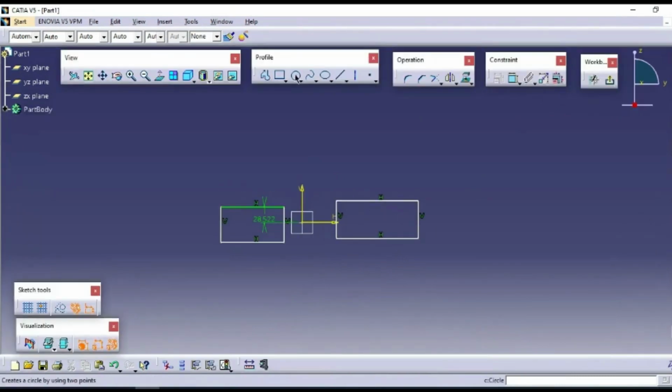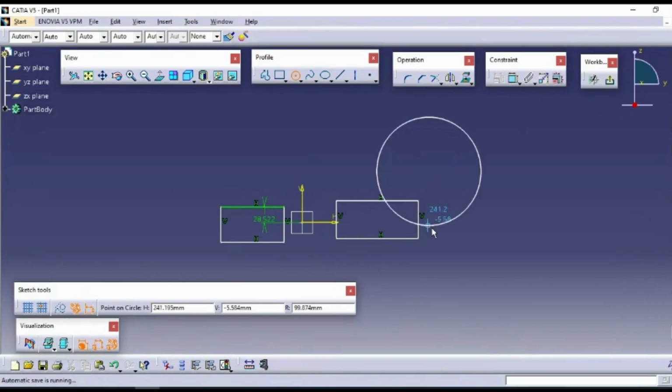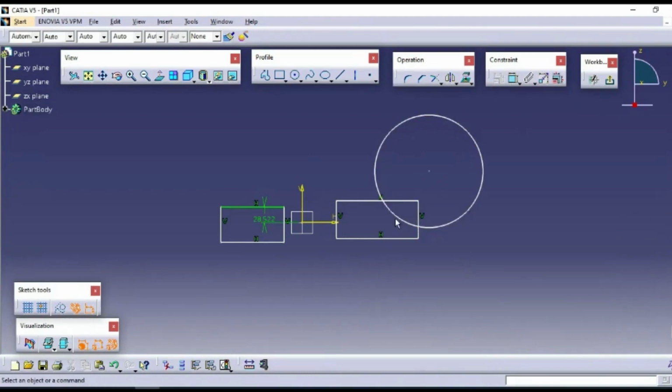And also, only one profile should be there. If you take two profiles like this which are intersecting and you try to do the 3D, it won't work. Okay, so 3D works in a different way. So if I give one 3D model, each projection, each component separately you have to create it. Okay, so this is about the profile tool, how to create it.